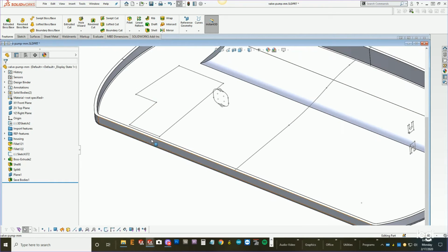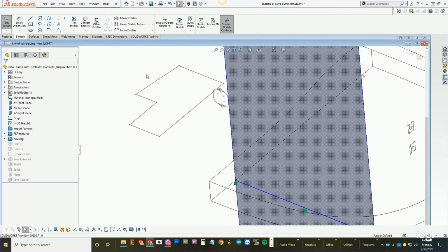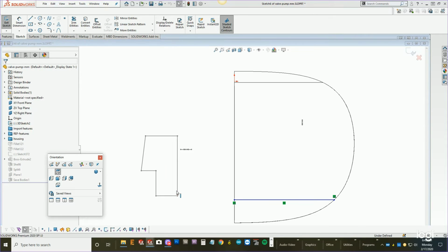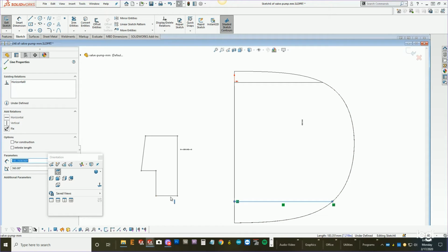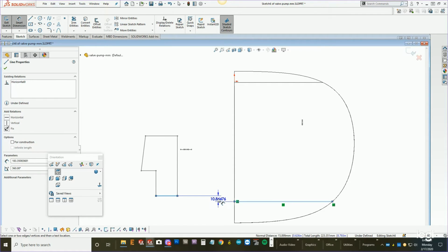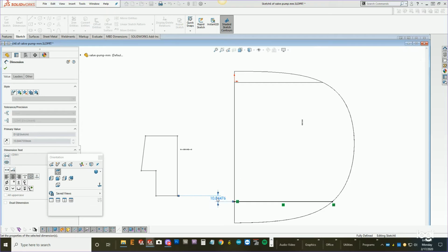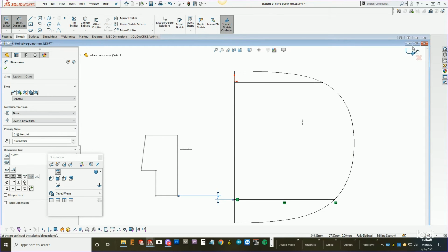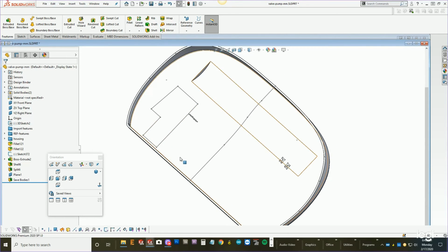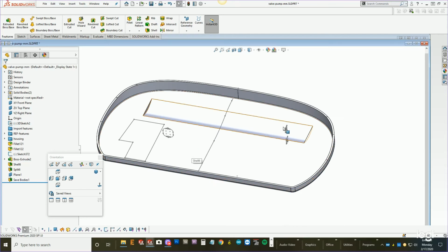to this wall. So let's use our breadcrumbs to find out where this feature is. Let me show my top view. And I know that I probably want to move this wall away a bit from that. I could even dimension it if I wanted to, from here to here, and say that I want it to be 7 millimeters. And now that I regenerate my master, I can see I have a comfortable distance or margin there. Let's go ahead and create a few more features and then go back to the assembly.